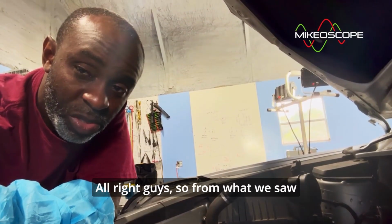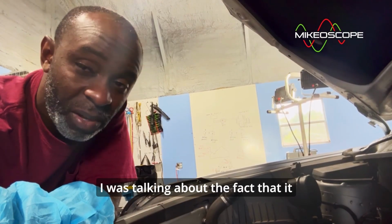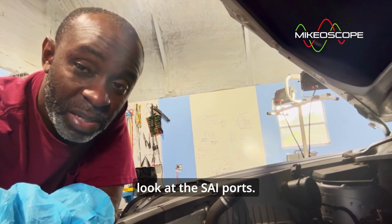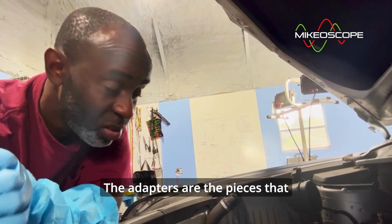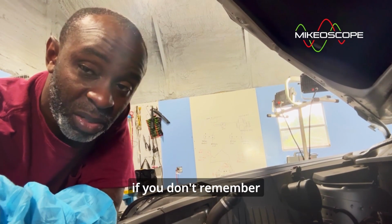All right, guys, so from what we saw with the valve on the right-hand side of the vehicle, I was talking about the fact that it didn't look good to me. It had a lot of deposits in it, and I was kind of concerned about it. I was wanting to take a look at the SAI ports. Now, in order to get to the ports, obviously you have to take both valves off, both adapters off. The adapters are the pieces that interface with the valves. You'll see them here shortly if you don't remember what I'm talking about.